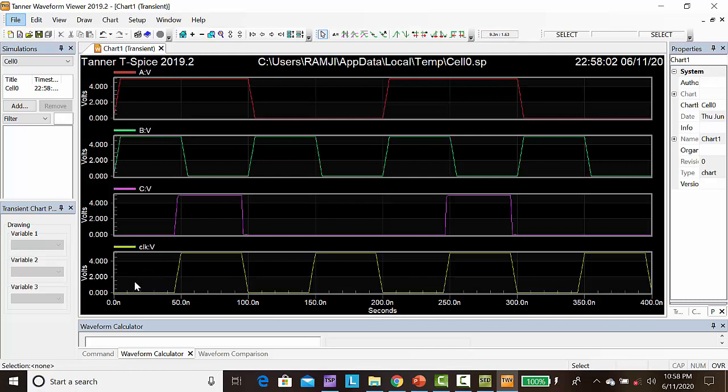So this is the pre-charge mode. In pre-charge mode, it will get the input. Now input is 1 1. For this AND gate, input 1 1 means output will be 1. So in the evaluation phase, this is the evaluation phase of the clock, we will be getting the output. Next, in this pre-charge mode, now input is 0 1.